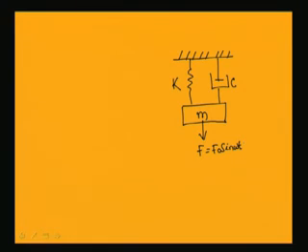So, this simple model can be a model of an IC engine or reciprocating engine. In a reciprocating engine, you know that there is always an unbalanced force. This is the crank, this is the connecting rod and this is the piston, and due to this reciprocating part there is always an unbalanced force, and due to that unbalanced force the base or the support will be subjected to some motion.